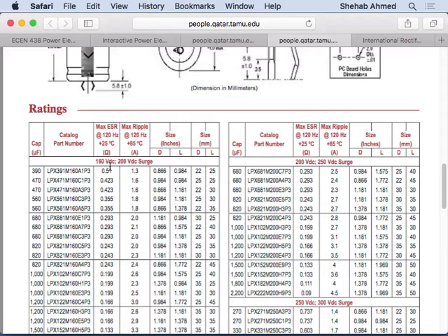This capacitor is mainly going to be used in a full wave rectifier application, and in that application it is charging and discharging at double the frequency of the input waveform. So if the input waveform is about 50 or 60 hertz, then the capacitor is operating at about 120 hertz. Charge, discharge, charge, discharge, charge, discharge. So that's why they gave it to you here.